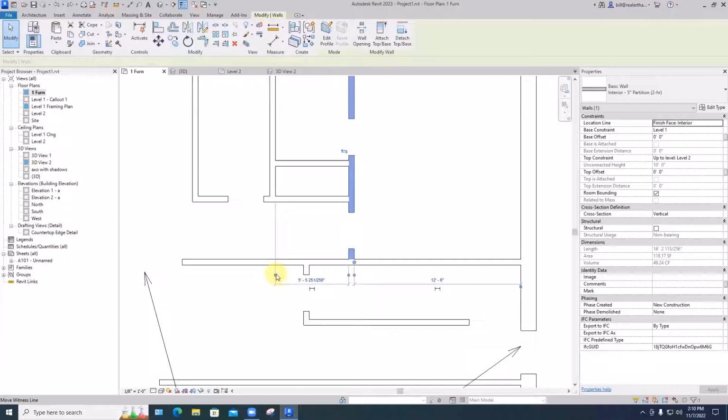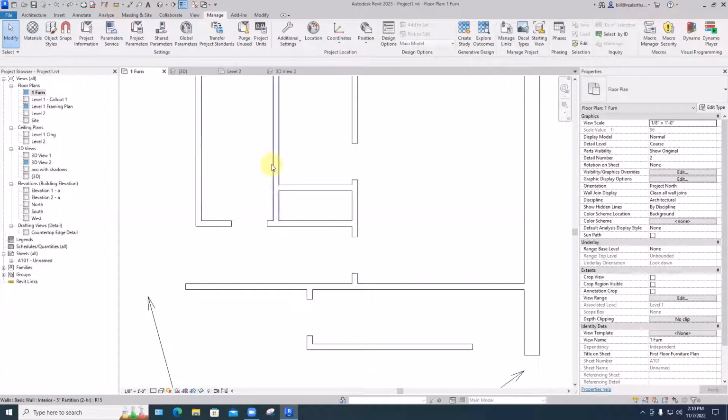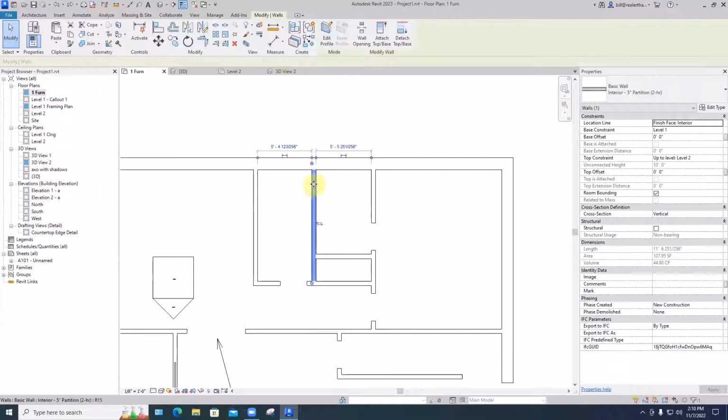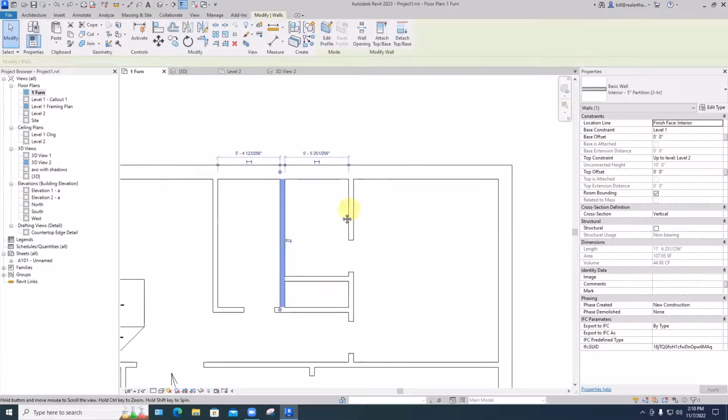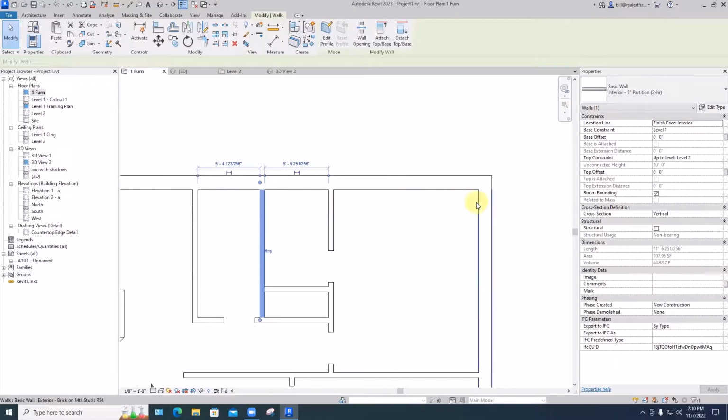So if I pick this dot and drag it over to here, it will then give me that dimension. It might be something I know, it might be something I'm trying to find out. So using that as a starting point, if I want to know how far this edge is from this wall, let's say I laser shot the whole thing and want to check it, I pick this dot and move it over until it clicks to that line. And now I know what that is.